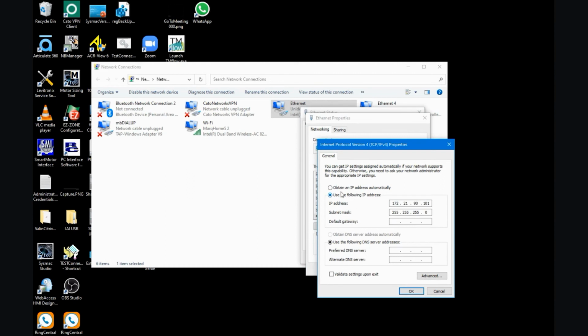Many times Office networking is set up so that when you turn your computer on, it'll obtain an IP address from the network automatically. And if you leave your IP address set to some fixed IP for the purposes of communicating to your PLC or your other devices, then you may not be able to communicate on your Office network.